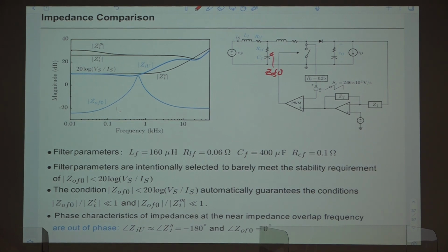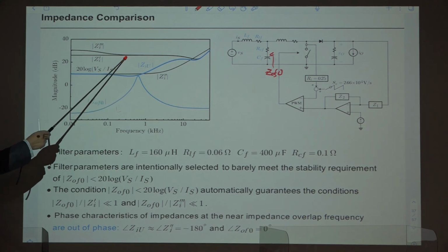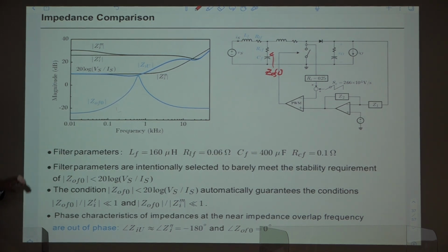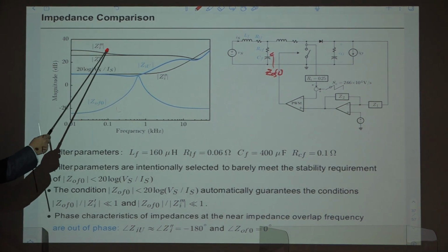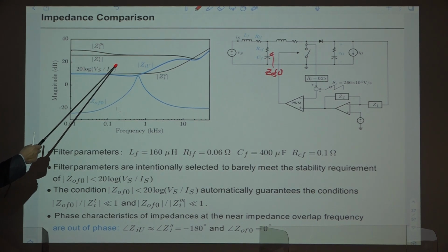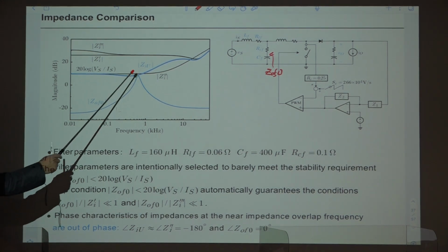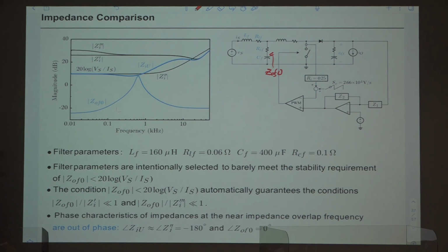very poor in closed loop performance. So the filter interaction will be pronounced a lot because of the nearness of this. Okay, but even with this condition, there is a sufficient distance between these two curves and this output impedance. So the performance criteria determined by the ratio of this and something won't be changed. But performance criteria related with these values will be changed a lot.